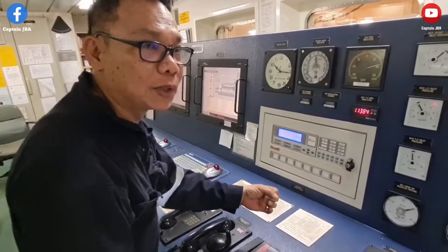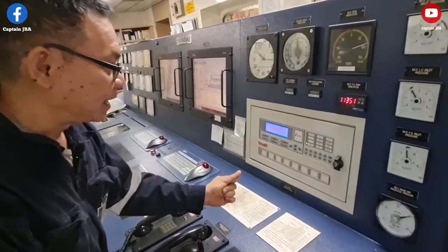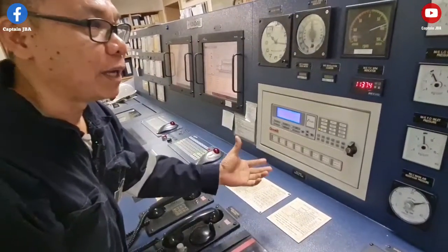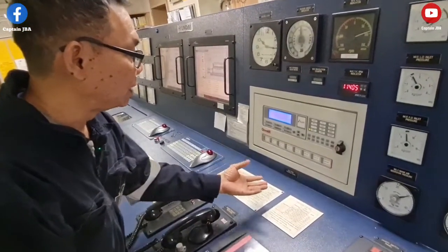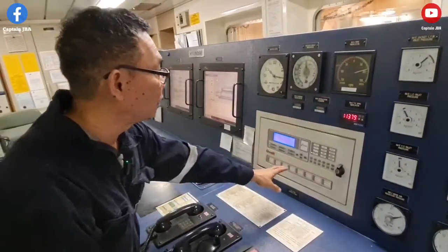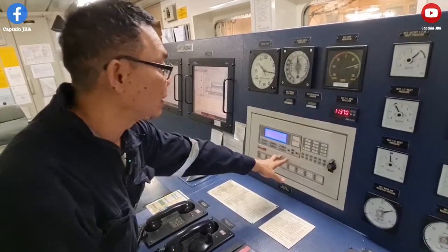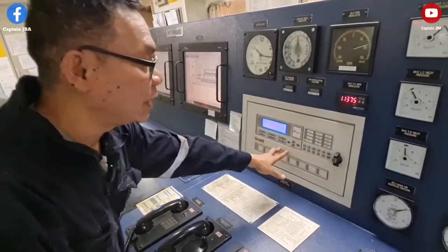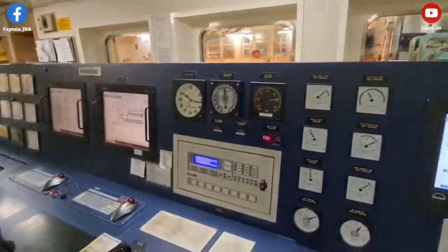Of course, it's mist that could come from our bearing failure. For example, it could create vapor inside the crankcase, and this will trigger once it reaches the setting of our mist detector in order to protect our main engine, and it slows down the main engine in case it detects it when it reaches this.